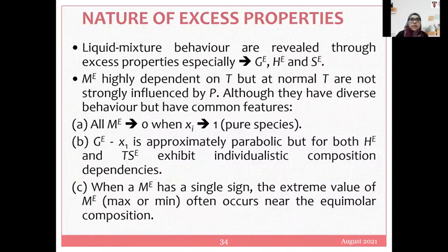And as the last, to conclude, liquid mixture behavior is revealed through excess properties. We can reveal the liquid mixture behavior based on the excess Gibbs energy and excess enthalpy, or excess properties. The excess properties depend on temperature but are normally not strongly influenced by pressure, although they have diverse behavior but common features. All excess properties equal 0 when a pure species is obtained in the system. The excess Gibbs energy versus the composition of component 1 is approximately parabolic. Basically it refers to this graph.